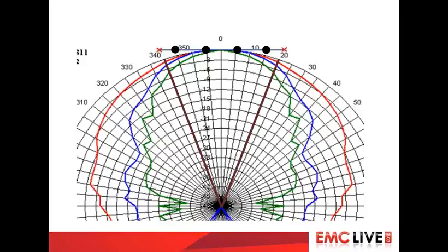Now this actually holds quite a lot of information. If you look at it, you've got your greatest power density, your greatest volts per meter at the bore sight. And then with distance to right or left, let's use the blue line, you can see that the illuminating power is dropping off as you go rightwards towards the rightmost red cross. So for instance, let's say at the extreme where the brown line crosses the blue line, we have, what would you say that's, 2 dB? We have 2 dB of loss. So although our bore sight might be at the intended volts per meter, in fact, at the right cross, and don't forget these crosses actually represent a circle that passes through calibration points, it will be 2 dB down.